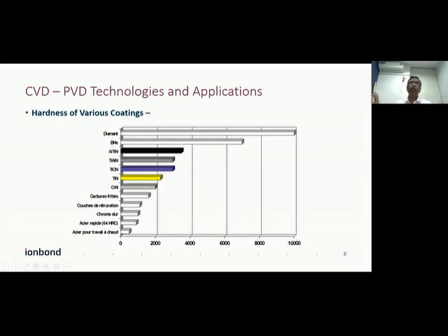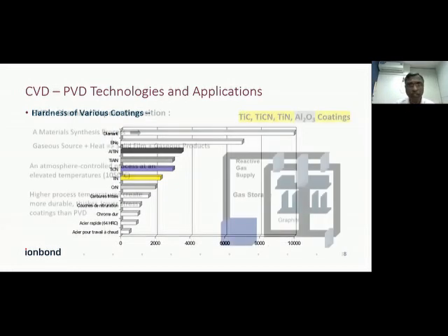So as we progress to smart coatings, we are able to have different hardnesses with different coefficients of friction, and all these can be tailor-made as per the application, whether it is a cutting tool or forming and molding. Different segments are there, like hot forging, pressure die casting, rolling, plastic molding. All these different applications require different coatings with different surface properties, tailor-made as per the requirement. So now I will start with CVD.